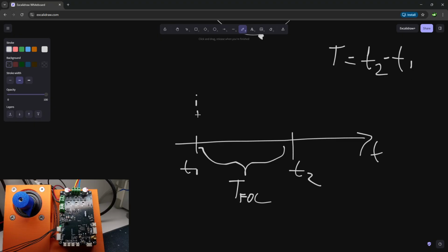In a perfect world, when everything works as it's supposed to, you would measure your ADC over the whole period and have an average value of the whole period. Then at the very end, you would use it for calculations and run the next cycle. This is a perfect world, but it's not possible.